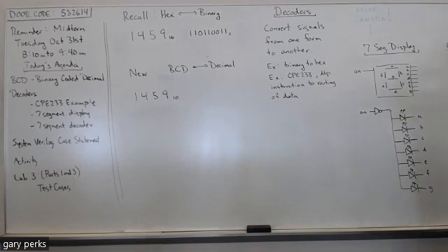This time, your top structural module will connect 3 modules together to make a circuit that adds 2 4-bit binary numbers. We'll display the result as a hex digit if the result is 15 or less, and we'll have blank displays if the result is greater. Anyway, that's the game plan today.